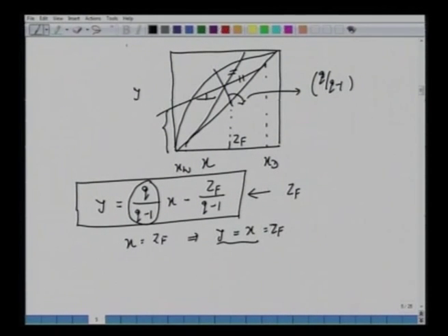Okay, so all we have, we had L bar as L plus QF. If Q is 0, L bar equal to L. Everything is vapor phase here. And we have G bar as G plus F into Q minus 1. So if Q is 1, everything is liquid, G bar equal to G. That means it's a saturated liquid.